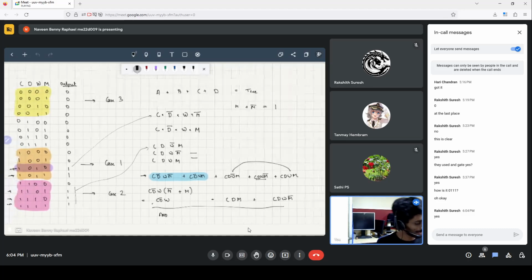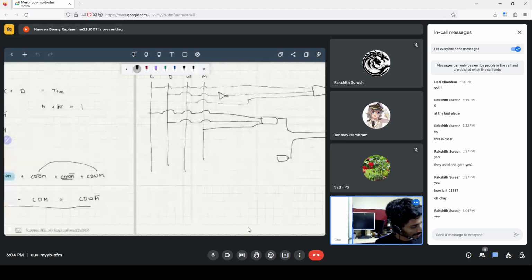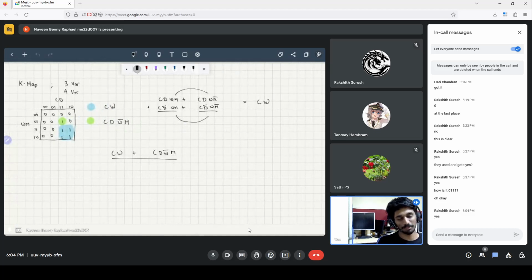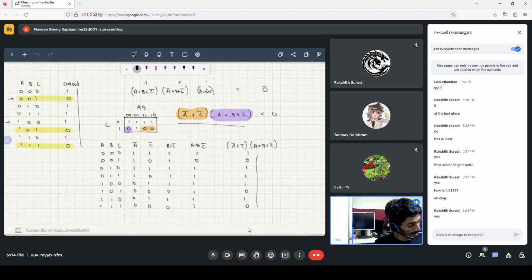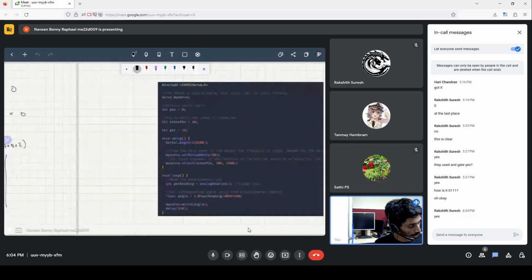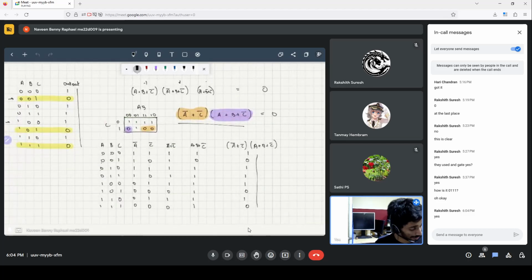Okay, so that's the concept of K-maps, and I'm repeating this because it's such a useful concept if you're learning about product of sums and sums of products. K-maps are essentially a really simple way to do sums of products and product of sums. As you saw, the map you draw depends on the number of variables. If you had 5 variables, say, then you'll draw a rectangle for A, B, C, D, E. That is a rectangle of 8 by 4.